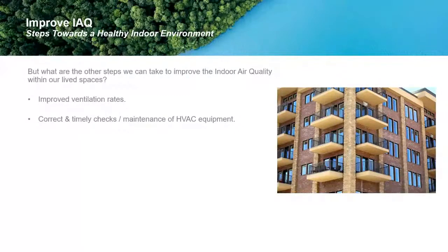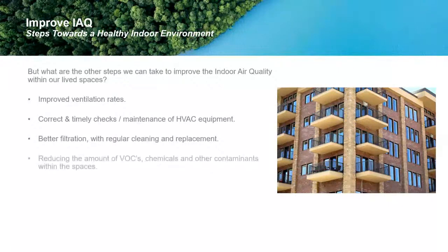So making sure all the seals and everything are in good working order, the alignment of the rotor is correct, and there's no breaks in the seal. Better filtration. Filter technology is coming a long way these days with the invention of HEPA filters and certain things like this. So making sure that we're getting a good level of filtration on the air that we're bringing in, but also making sure that the filters are checked, cleaned, replaced wherever necessary, and trying to avoid any filter leakage, filter bypass leakage.